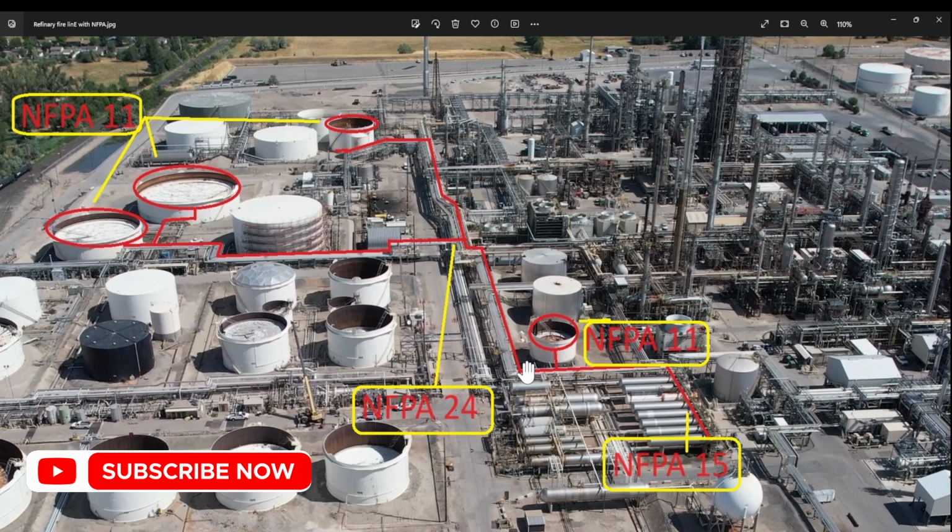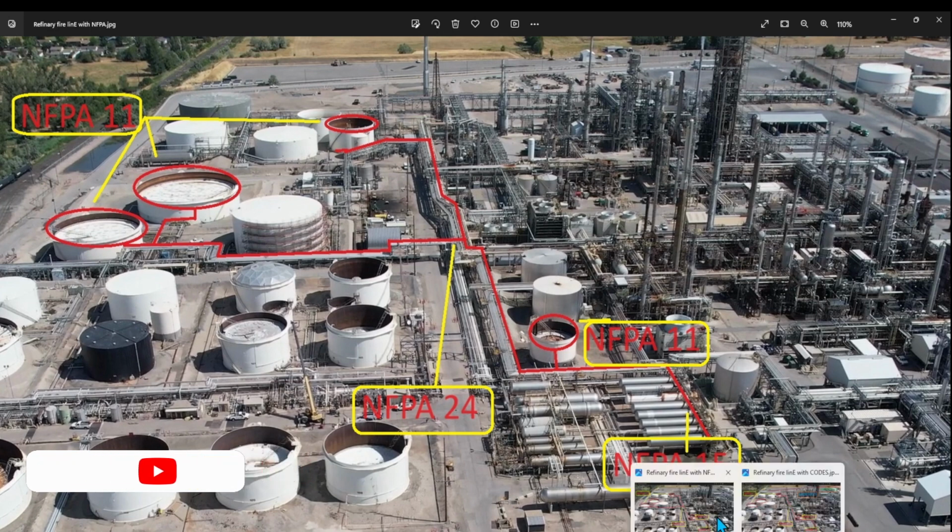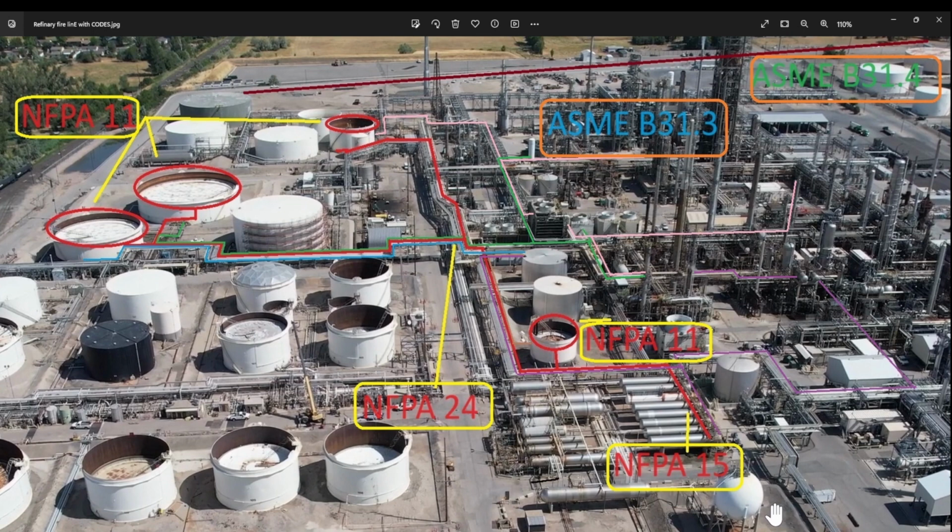Now, if welding was the only consideration, this would probably not be an oversight. However, when we look at the complete project scope of work of all the piping, we also now see the ASME B31.3 piping running throughout the facility. So here you will have normal service, severe cyclic, and category D for weld grading.